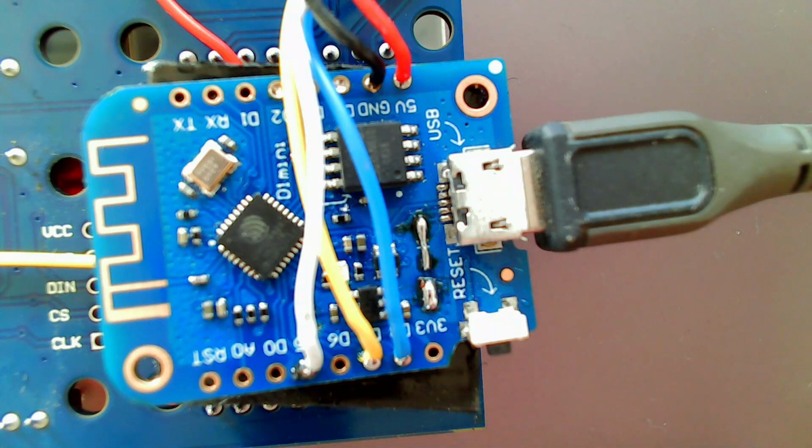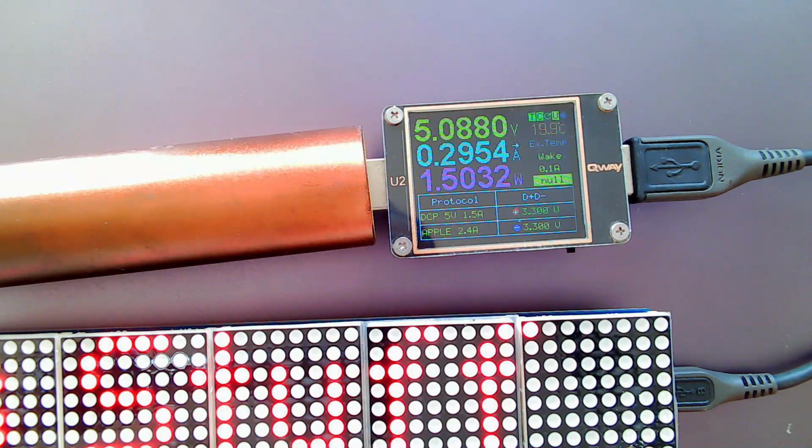As mentioned in the first part of the video, I skipped the fuse and the diode over here. You see the big solder blobs in the middle of the screen. I will probably get away without doing that, but I didn't want to risk blowing the fuse with a current higher than 500 milliamps. This is my solution and I stand by it. And while I was panicking about current consumption, the whole shebang right now draws about 300 milliamps. So this would have worked without any modification on the WEMOS D1. You're pretty much safe if you choose the same settings as I did.